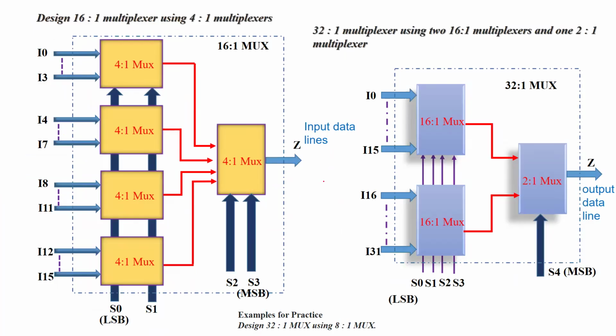Let us move to the final slide. Here to the left side, we have got wonderful pictures where we are making a 16:1 multiplexer using only 4:1 MUX. But remember here and notice, we haven't used an OR gate or any logic gate. It is purely only 4:1 MUX. So 4:1 MUX, we need them in the quantity of 5. 1, 2, 3, 4, and 5. So we've got 5 chips of 4:1 MUX. Together they are making 16:1 MUX.